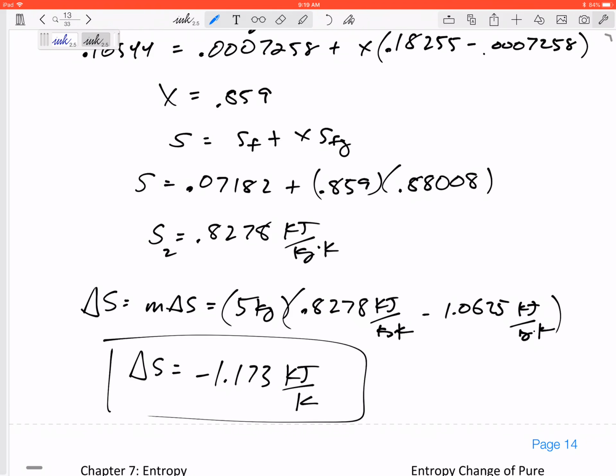Yes, because that is just the entropy change of the refrigerant. We didn't look at its surroundings. Also, it wasn't isolated. It was being cooled, so there was some heat loss. It was being stirred. There is work and energy crossing the boundaries. So it's okay if the entropy of something is negative. It's only when we're looking at the total entropy of everything that it should be positive.